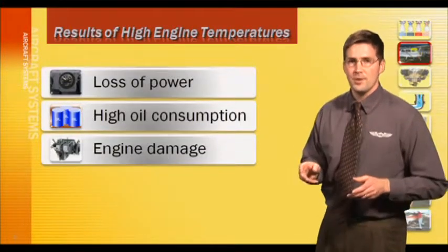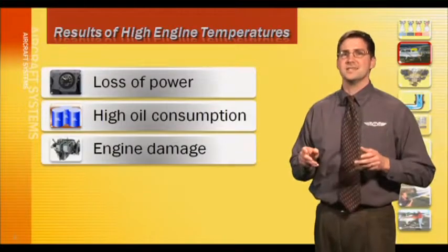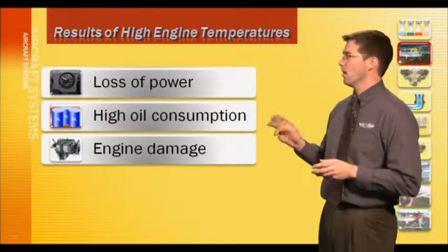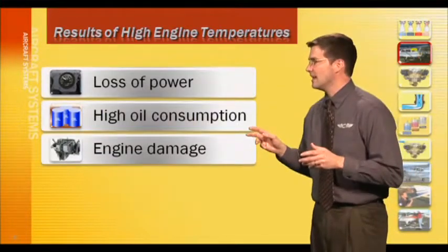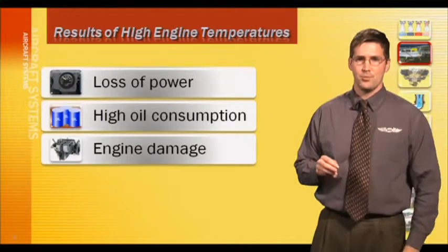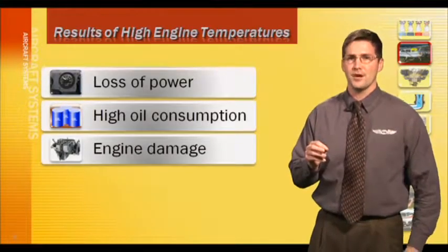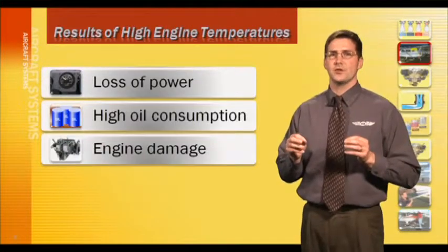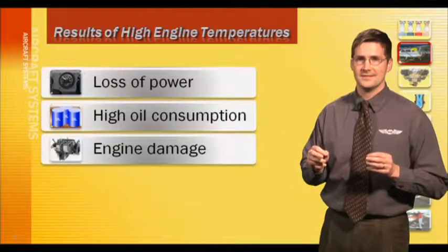Because of the many moving parts in a reciprocating engine, as soon as the engine is started, power should be set to the recommended warm-up RPM. Then, the engine gauges should be checked for the desired indications. It is important to check the oil pressure for operation within the manufacturer's time limit. If you don't see the instruments in the green, shut down the engine.